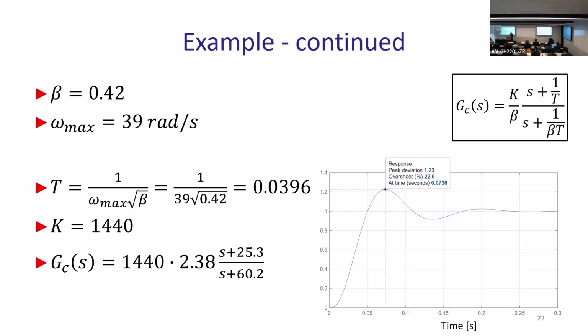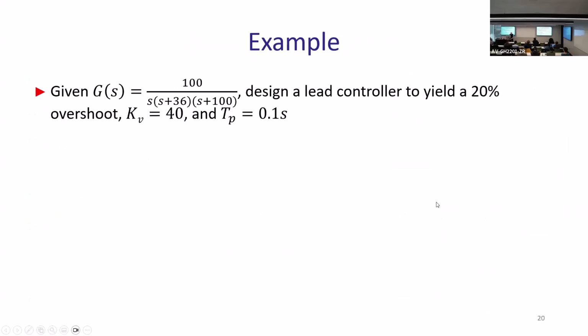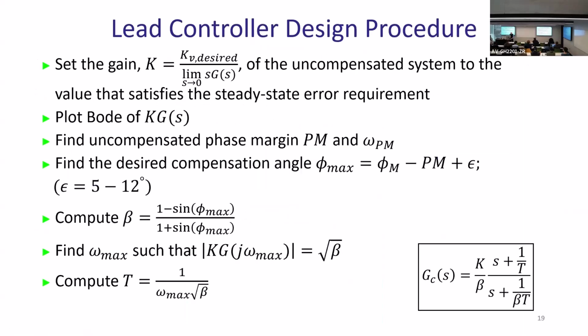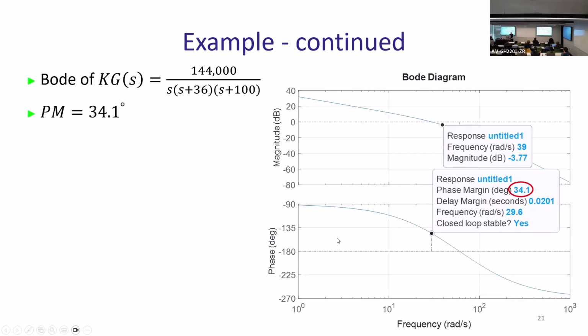All right. And as you can see, peak time is close to whatever you wanted. You wanted 0.1. Now it's 0.07. So peak time is satisfied. It's one of the requirements. You got it right. Now, also bandwidth should be fine. If you're looking at that point, where it gets you to the 3 dB, here will be much farther than something that you wanted. What's the number? I wanted 46. Okay, it's broad enough. So it passes all of the frequencies.